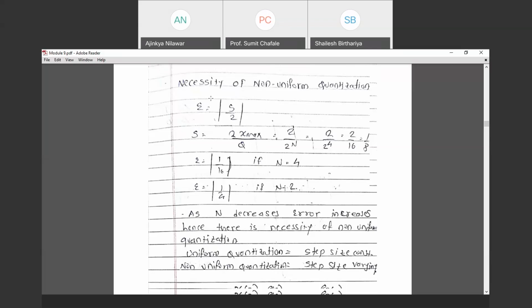So here you will see what exactly we are doing. We first generate a 1-bit staircase with the help of the quantization block, and then we check the variation, that means delta. How are we checking? Current sample minus previous sample. If the current sample is greater than the previous sample, then 1 is sent. And if the current sample is less than the previous sample, then 0 is sent. That means only 1s and 0s we are sending.